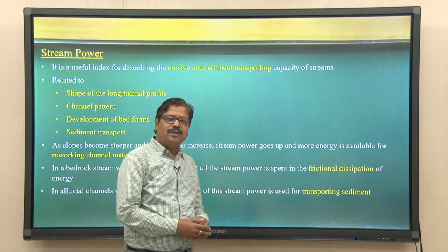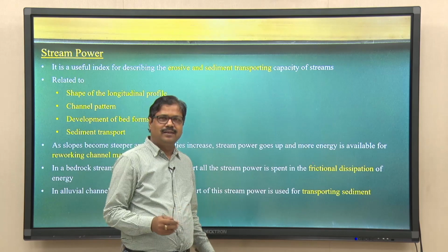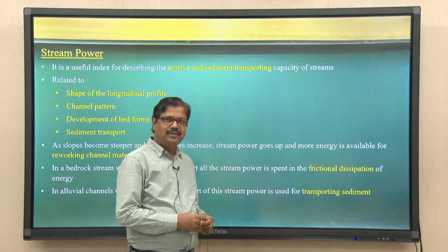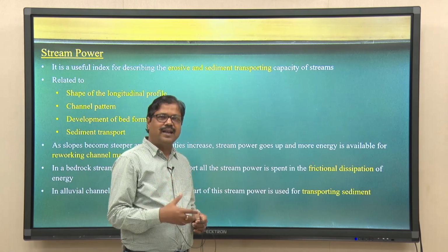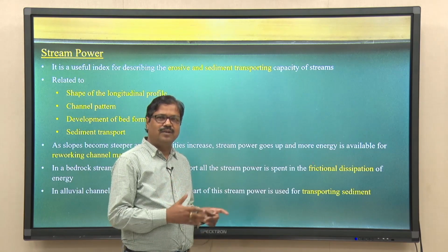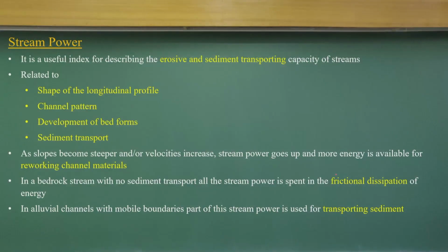Another point I want to introduce is stream power. Stream power is nothing but the potential energy loss in a stream of length L. That clearly indicates that based on stream power we can know how much sediment transport capacity or erosive power the stream has.